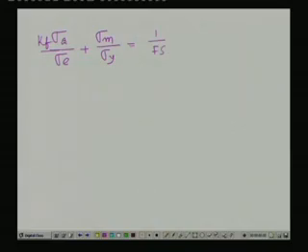So, what is this one? We know that sigma A, the stress amplitude, by endurance limit, plus sigma M by the yield point, equals 1 by Fs. You modify the stress amplitude by the factor Kf. So, what is the shear stress amplitude here? This is equal to 0. So, this term is not coming into the picture.